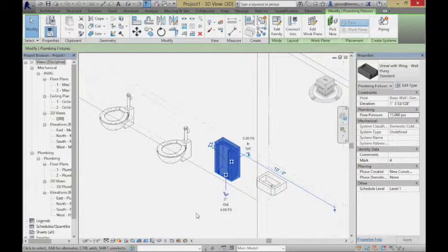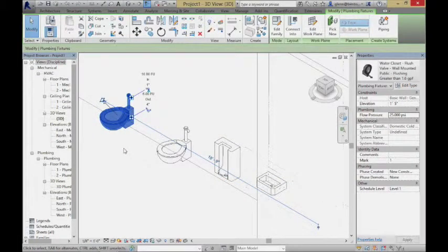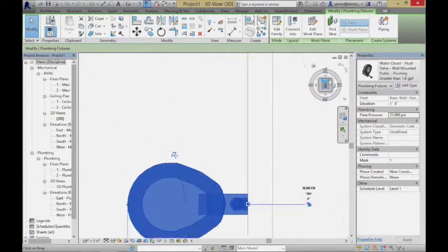Okay, so if I want to start with, for example, the sanitary system, let's think about that. I'm going to want to put some line in here. I'm going to put like a 4-inch sanitary line kind of coming across the back over here. But I know it has to be at least 4 inches because the toilet's going to require a 4-inch out. So I'll go for a nice 4-inch system. That'll probably be big enough to take care of the capacity. If it needs to size it up, ultimately Revit will tell me. We can actually get it to size things based on the total number of fixture units. So let's go ahead and put this in.